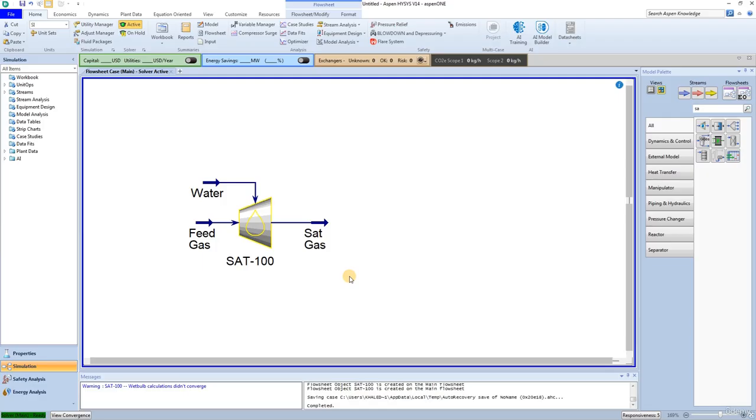Task 2. Acid gas removal and dehydration. The first stage of the LNG process flow sheet will be to remove the acid gas components and then dehydrate the gas. This is an important first step, as removing the acid gas components will make the natural gas stream far less corrosive. Removing water will prevent the formation of hydrates, which could otherwise clog piping and equipment and cause other operational hazards.